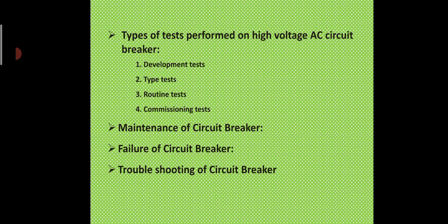Now, maintenance of air circuit breaker. It is checked during the routine maintenance: operational checks, visual inspections, cleaning, insulations, circuit breaker enclosure, main and arcing contacts, arc control devices, mechanisms, auxiliary switches, indicating devices and interlocking, isolating contacts, overload devices, and protective relay, instrument and protective transformer, control relay or contactors, main connections, etc. These are the regular routine maintenance items of an air circuit breaker.